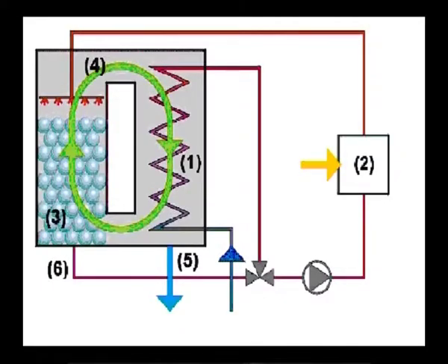Hm is determined by the flow field around the material being dried, in meter per second, which may be viewed as a velocity of mass movement. When this vapor concentration difference is positive, vapor leaves the material and thus drying occurs. The reverse is the wetting or humidification process.